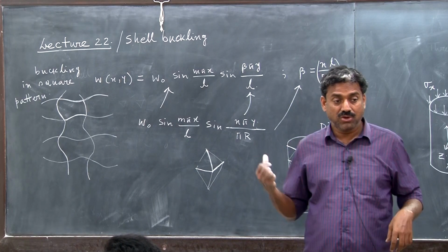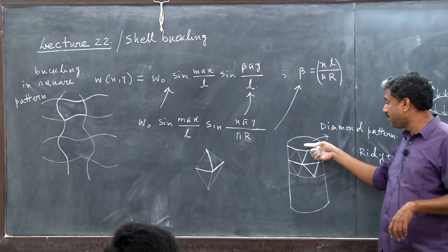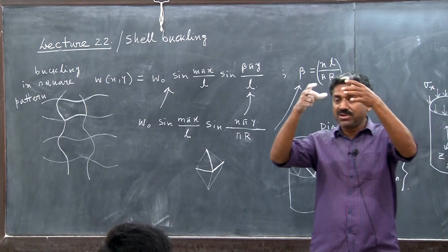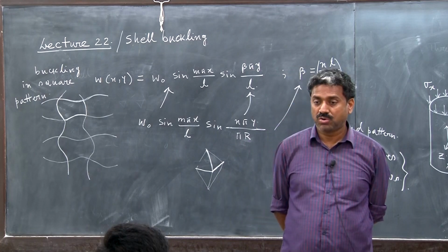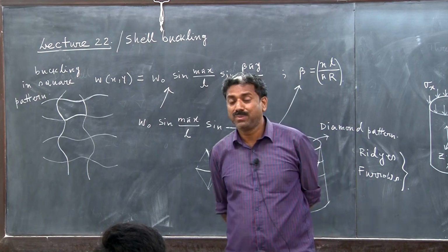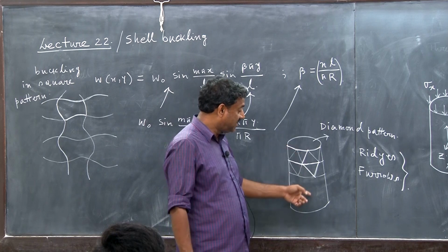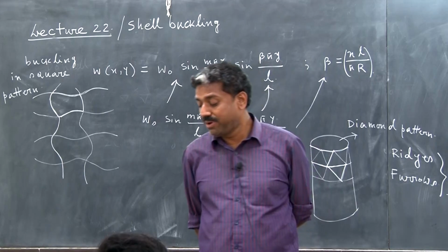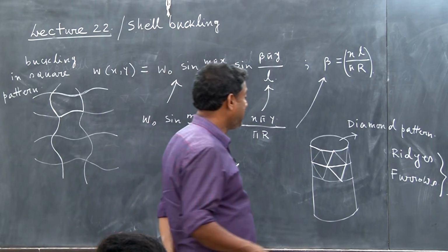In order to develop this pattern, it will be mounted on a mandrel, radially supported, and then gradually you apply the load using, of course, a displacement control or strain control experiment. And gradually this pattern will develop. If you do not do this, then you will not see this beautiful pattern from the end propagating over the length.